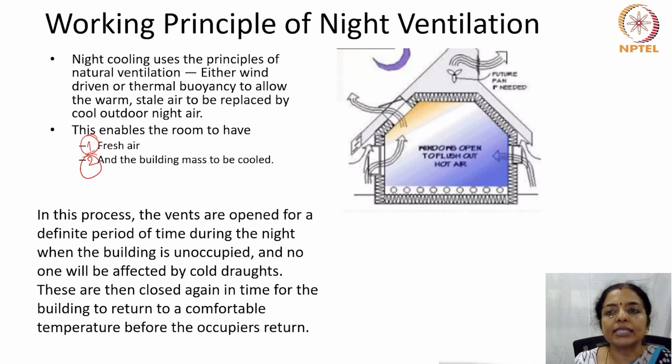In this process, the vents are opened for a definite period of time during the night when the building is not occupied and no one will be affected by the cold drafts. Then these are closed again in time for the building to return to a comfortable temperature before the occupiers return to the building. So in this concept, at night, the openings are all opened up for cool air to enter the building.